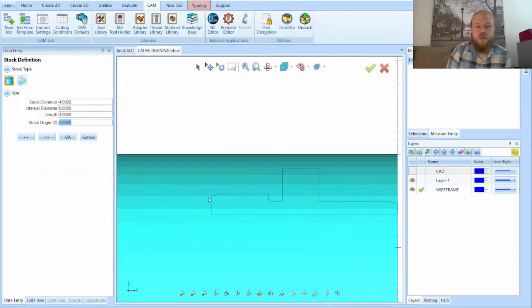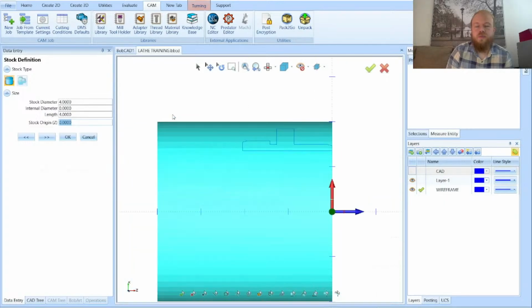And then we'll do a cutoff operation and see some advanced CNC lathe strategies to be able to cut down on air cutting, cut down on cycle time, setting our feed rate, or we could set constant surface speed, those kinds of options today.